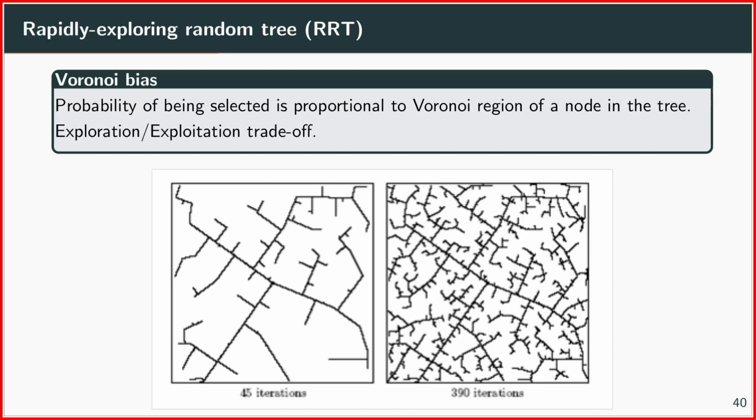And so what the RRT is doing here is first trying very, very hard to explore the whole space as quickly as possible. And once it has a good covering, like in this case here, then it would go into this exploitation phase where it would fill in smaller and smaller parts of the tree, and it would show you this more fine-grained, finer resolution tree in the end.